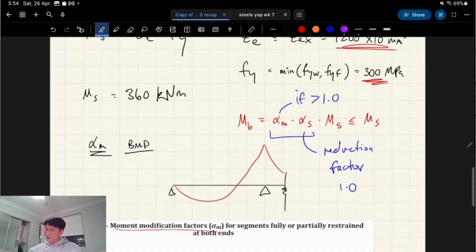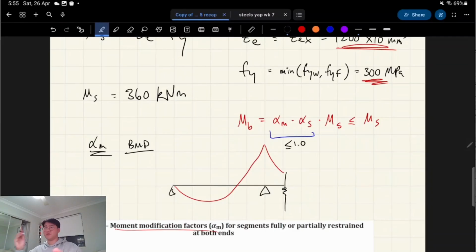So imagine you have this percentage bar, right? MS is 0. If you had this scenario going on of your multiplication factors, you've essentially crossed over your allowable bar and you have to set it back to that, right? You have to shrink it back. So that's a scenario which can happen, right? So you have to be careful about what the product of these two things is, because the product of these two things has to be less than or equal to 1.